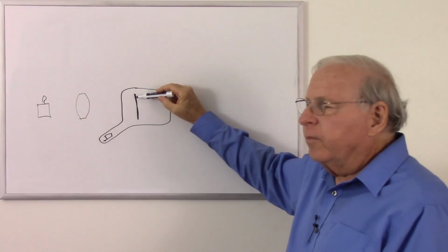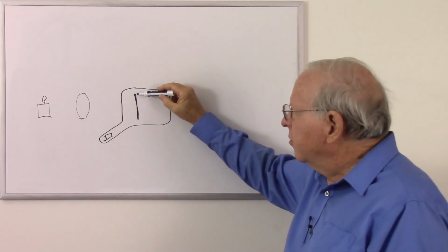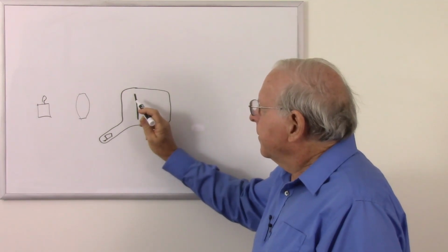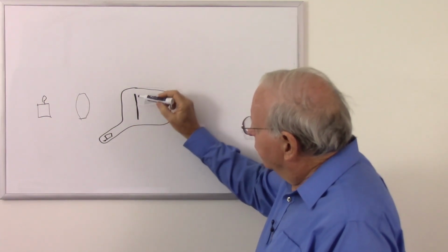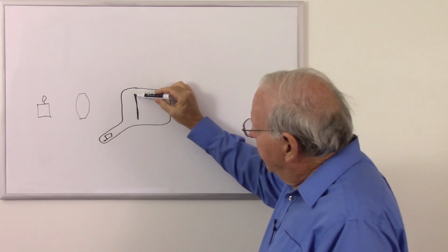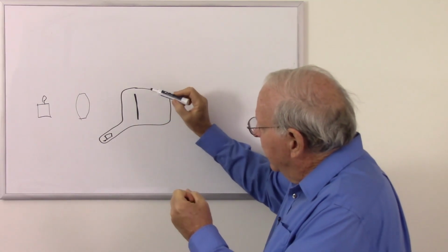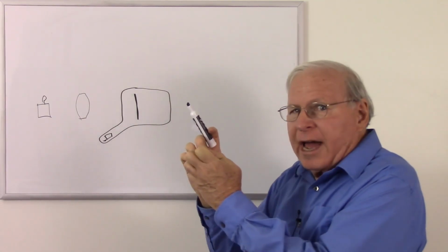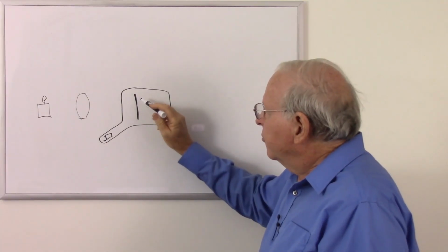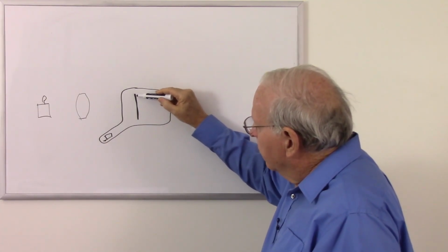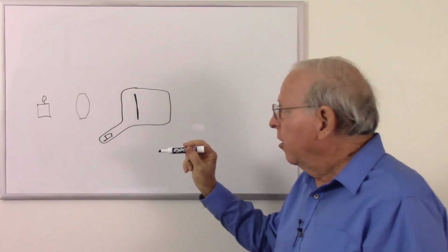And this was coated with material that included silver but had other materials in it too. I think also had cesium oxide. And worked on a completely different principle. When they made it, by baking it in an oven, and this was actually discovered accidentally, with the right amount of heat, the material would crack into small parts, and with another material coated on the back, it formed little tiny capacitors that could store charge.